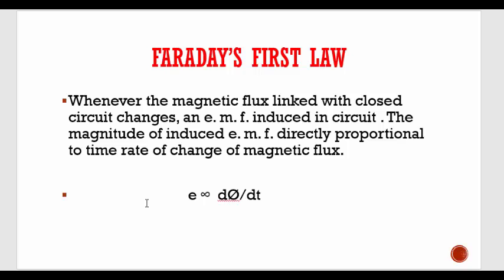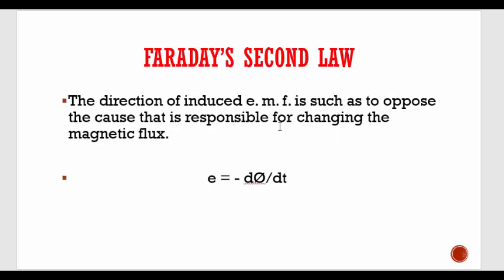Now, what is the second law? The second law is also important. The direction of the induced EMF always opposes the cause that produced it. What is the cause of the induced EMF? That is the change in magnetic flux. So it opposes the change in magnetic flux.